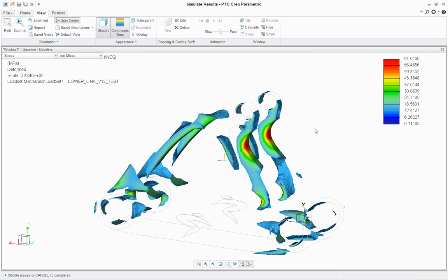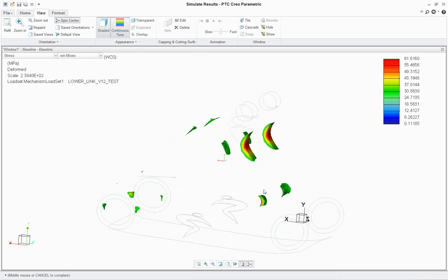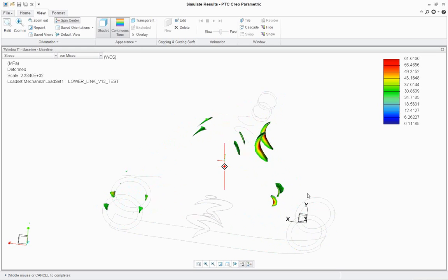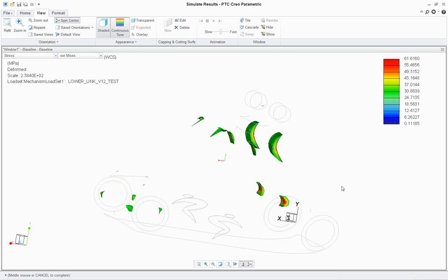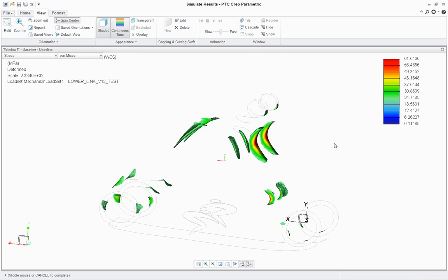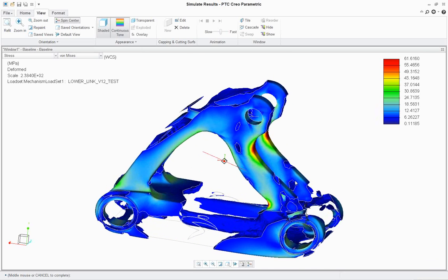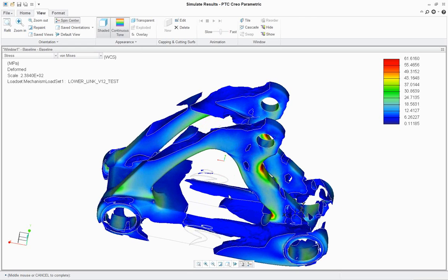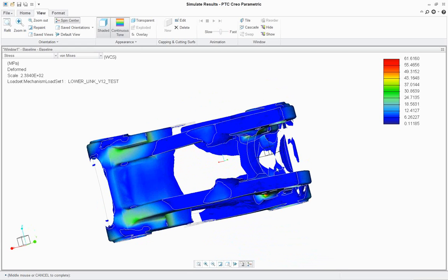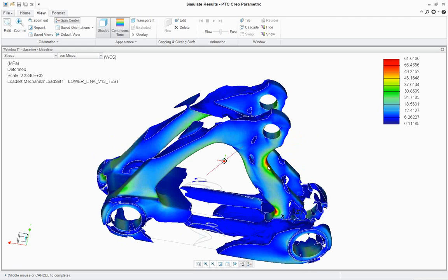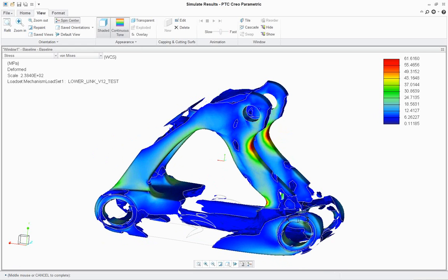And also, if I remove a lot more material, right around that neck right there, and also right around this bottom neck over here at the bottom where I have those red areas, right? And then next up, as I begin to fill in more material, one of the things you'll see is the last place to get filled in is this middle section right here. And so those are some of the least stressed elements in the entire model. So not only does it tell me where my hotspots are, but it also shows me where I'm not really having that much stress. The material is not really bearing that much weight.